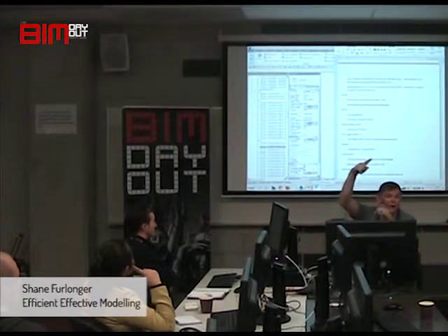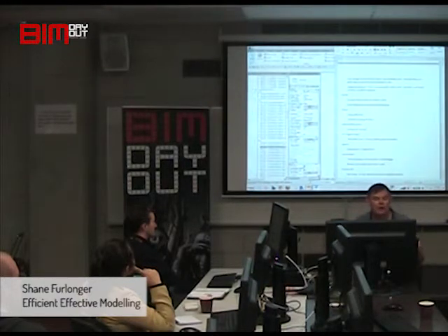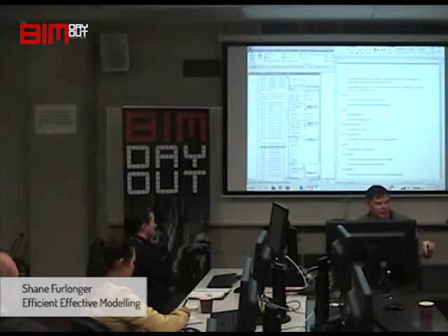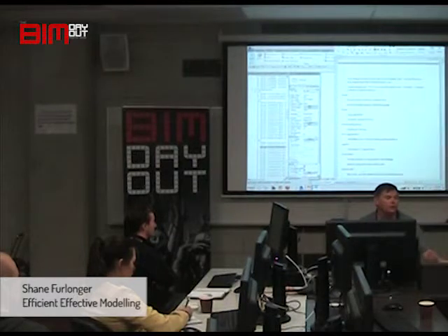And as soon as you change it in one level, it'll change in the level below and you'll end up with walls coming through your ceiling and something stupid. So, another big problem with groups in that instance is if you want to make a global change of your door type. Yeah? Can't do it.